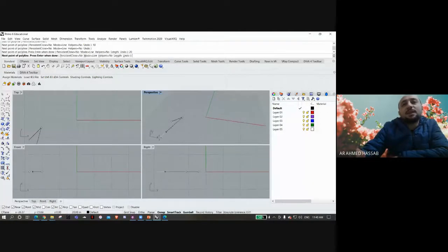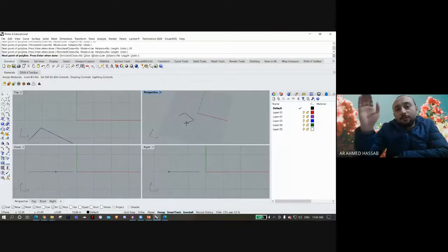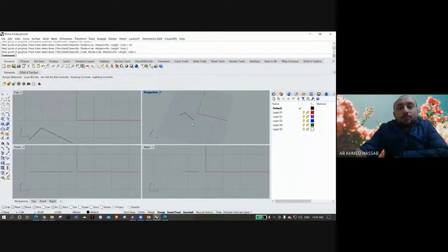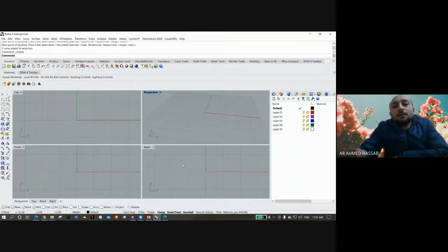This means the black line is stuck to 20 meters, and wherever I am in the viewport, it is just 20 meters, and I just follow up and click in a place to put the point. So firstly was the units, meters. You can see it down here.